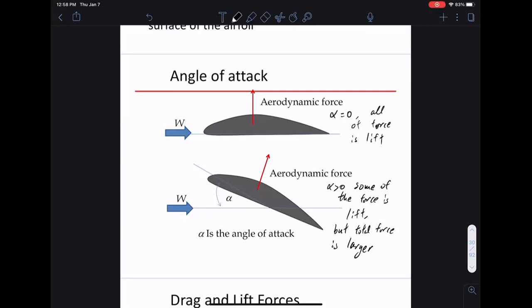That's why you can stop a wind turbine from generating power even when the wind speed is very high. You pick an angle of attack such that you have no lift, then you generate no power. The power of a wind turbine generator cannot be increased past its capacity, but can easily be decreased by changing the angle of attack. We'll see more of this in detail, but the basic idea is that angle of attack is a control variable for the amount of power generated.